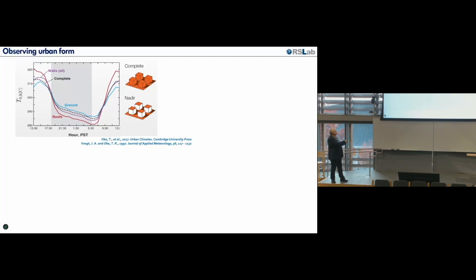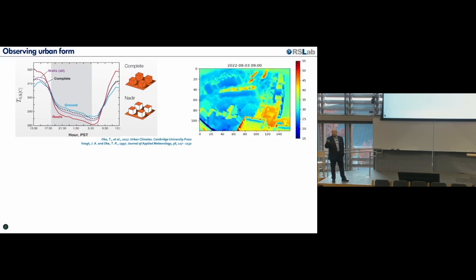You can see the evolution during the day. And you see the dotted line is close to the blue one, which is the temperature of the vertical facades of the walls, because the majority of the urban surface is vertical. And the green one is the temperature of the roofs. And here is a clear underestimation during the night and an overestimation during the day. And you can see here clearly this overestimation.